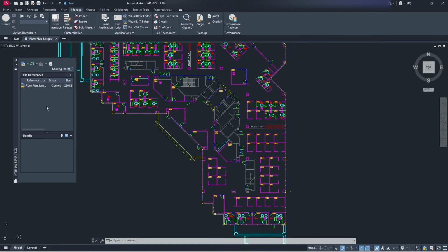So, when working with drawings that contain XREFs, you'll be able to toggle this new switch that will tell you if there's any missing references in this pane here. So this view will exclusively show the missing external drawing files. So literally it's going to show you which files are missing from that XREF. I don't have any XREFs that I'm missing right now, but you can literally just toggle that and it will show you the missing references.